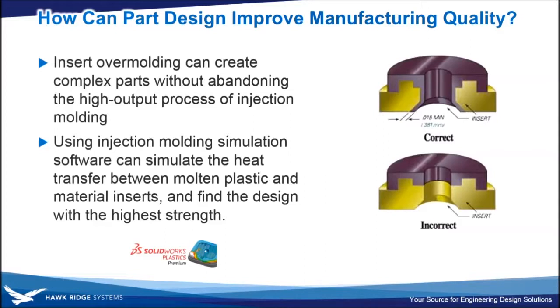And so injection molding software, in general, of course, can simulate what the filling and packing and cooling phase of that cycle looks like, and tell you roughly what the quality of the part will be, and if there are changes you could make to the material or to the gate location to get a more easily manufactured part and higher quality part.